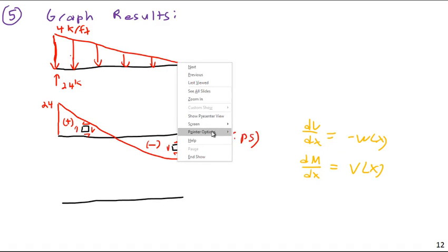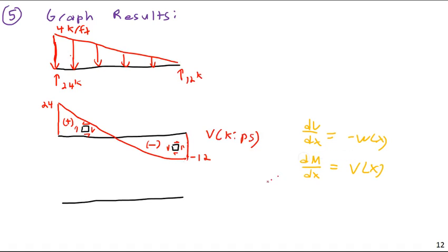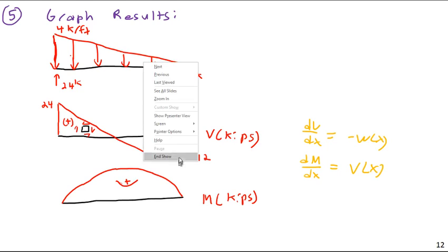So then, here, I'm going to plot the moment, M, and I don't have the number in front of me. To find the maximum, it wouldn't be that difficult. But anyways, it's going to look something like this. It would actually be a third order equation, a cubic equation, but it would still look something like this. So this is going to be positive bending throughout. This is positive moment throughout.